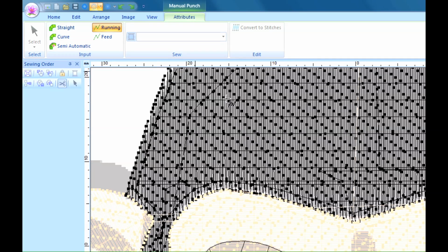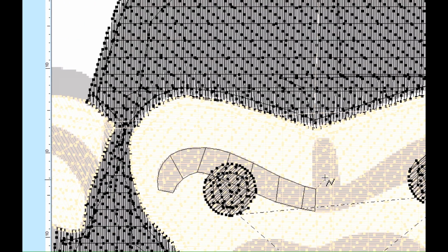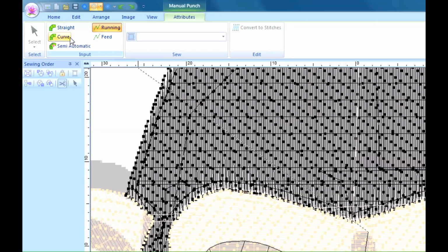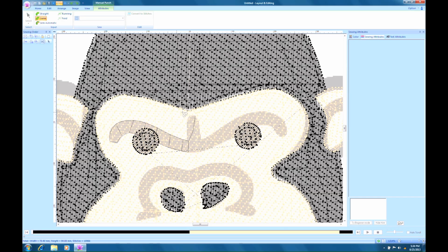You can also press the V key while you are entering the block or select the Running tool to choose a running stitch. Skilled use of the running stitch allows you to create data that reduces sewing time. If you use a running stitch, you can expertly adjust the direction of the block stitching.